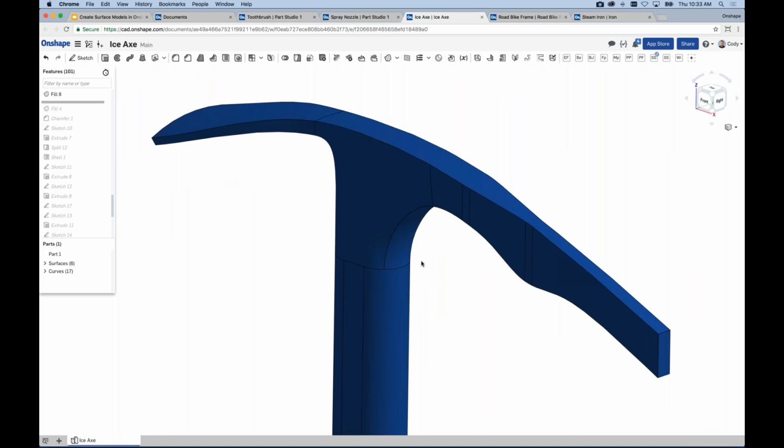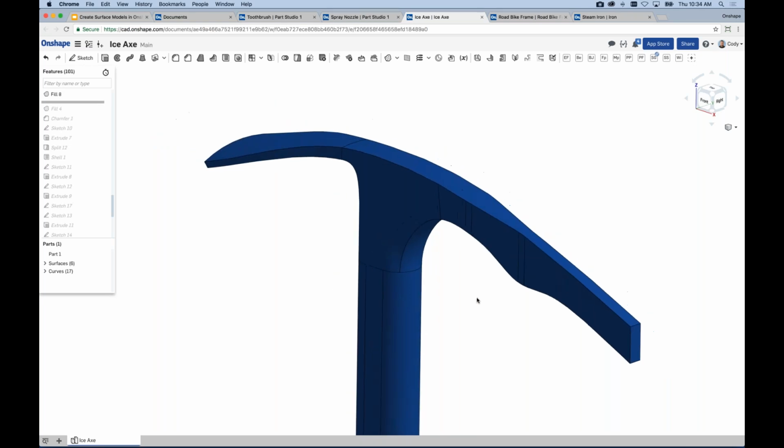It really takes an open surface and it will patch in a surface to fill that. Even if this is a scenario where Loft really isn't useful because I need many different edges. It could be a combination of 8-10 edges and even more. And so just keep in mind, fill is really an essential tool in those kinds of scenarios. There's not much else that will replace it. All right, so that is the fill command.